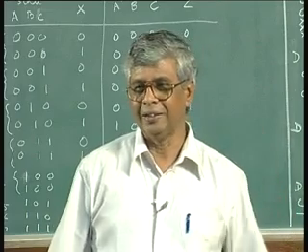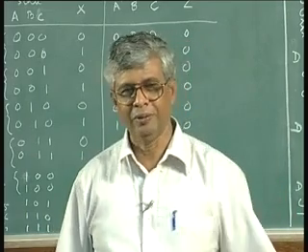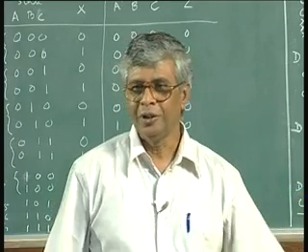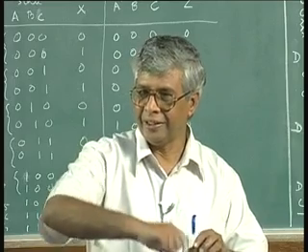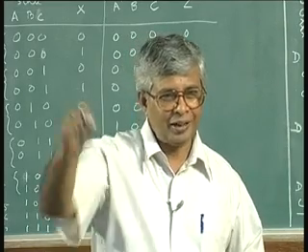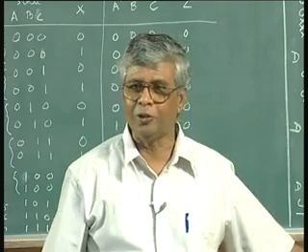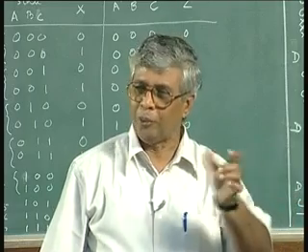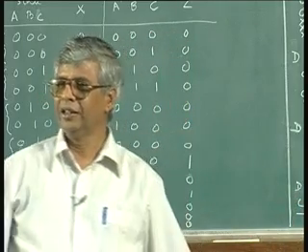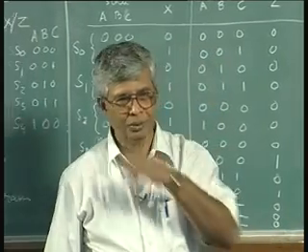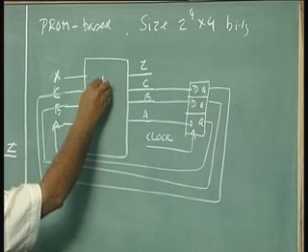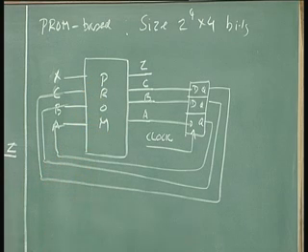So 2 in 1. Similarly, muxes are 2 in 1. These flip flops are 2 in 1. So anyway, I have to buy 2 flip flops and then a 3rd flip flop. I need to buy 2 chips. So, you can as well buy a 4-bit register, because a register has a common clock for all the flip flops and 4 inputs and 4 outputs. That is what I want. Sometimes you think you are saving by buying 3 flip flops, but you will end up saving if you buy a 4-bit register, correct? I told you this several times earlier. Anyway, so all I have to do is to program this ROM as per this table.